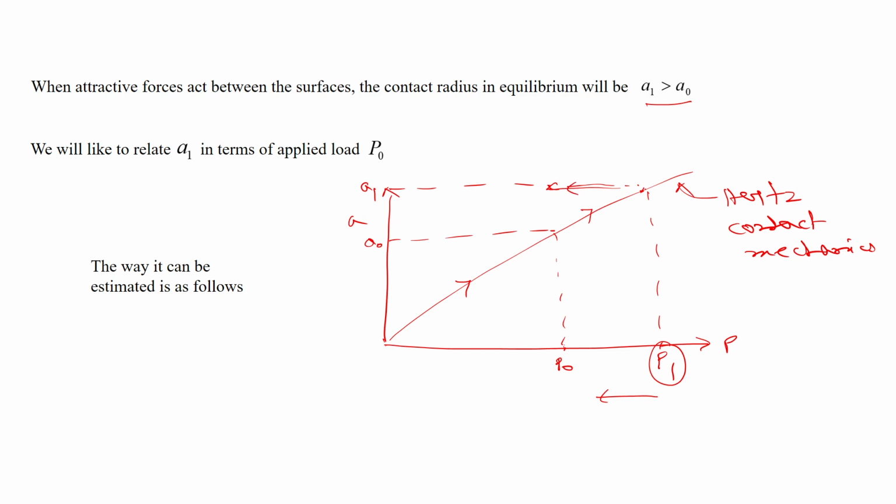Remember that in that other pressure distribution, in which the radius of contact remains constant, the pressure distribution for this particular case is P0 dash divided by the square root of 1 minus r square by a square. The radius of contact A remains constant at A1 here, and we decrease the pressure from this P1 to P0, because finally we have P0 here and A1 here, that is all. So, we have to reach this point.